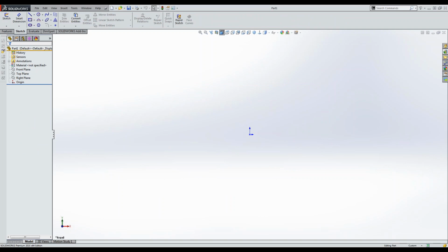Now here's where you want to, it might not be too big of a deal now, but later on down the road, when we end up adding this part into an assembly, it's important to take note of where we select our front, top, and right plane. What I find to be very tremendous in helping with assembly modeling is to model with planes instead of faces. And we'll discuss this in a little bit and talk about its benefits. So let's just make notice for now of the plane selections that I chose. And it'll come into play later on as we move through the part.